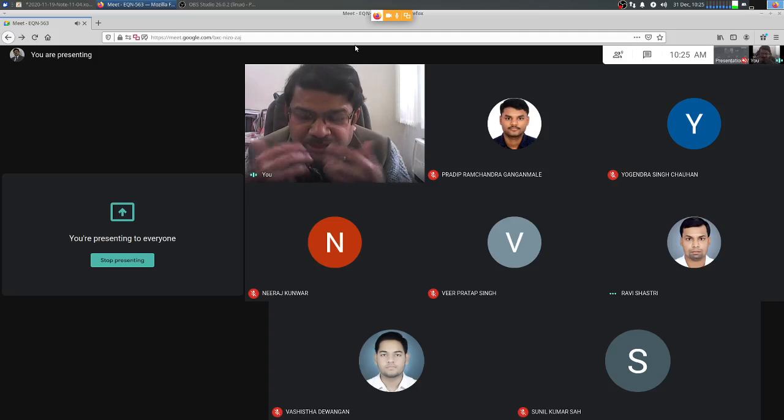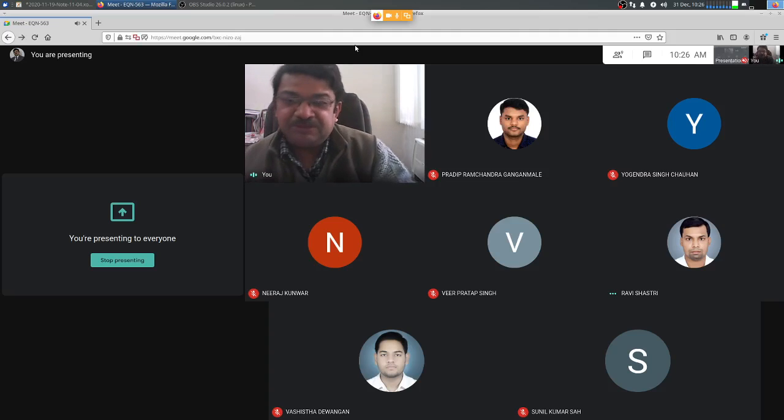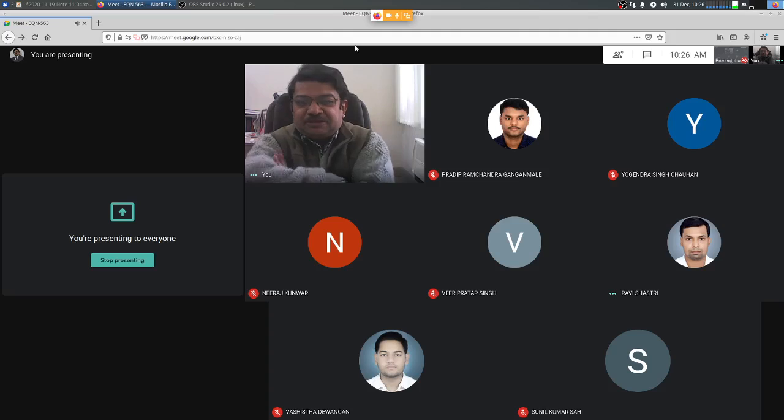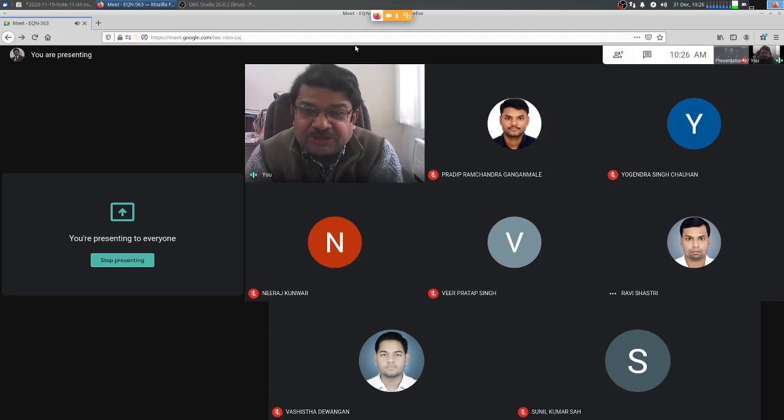So for calculation of mass, we do not ignore the flange. I am arriving at the flexural strength. Normally we ignore the flexural strength contributed by the flange action, and that is conservative for gravity load design. But my statement here is that ignoring that contribution of flange action to flexural strength is disastrous for earthquake resistant design.